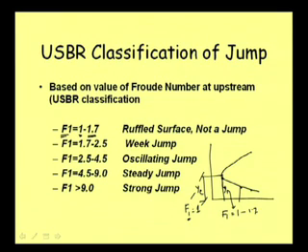Say, maybe for this y1 we can say that Froude number 1 is, suppose, 1 to 1.7, let us consider like this, I mean maybe up to a certain range. Now, within that range, what will be its corresponding y2? If I extend it, it is just this point. So, the difference between y1 and y2 is very, very small, and too there will be some wave formation, so that you cannot distinctly see a water jump or hydraulic jump there, because the difference of these two levels is very small.